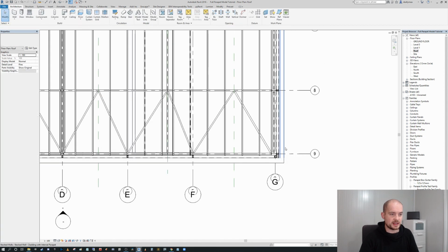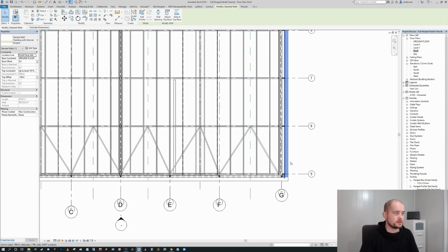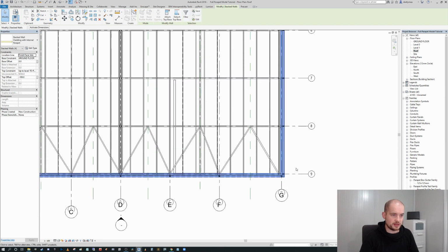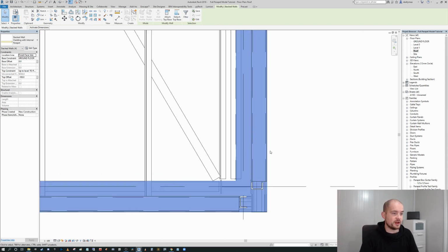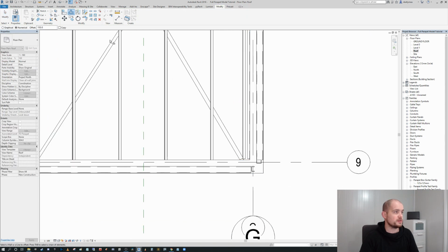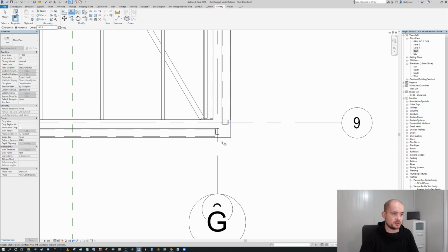And as you can see, that's actually after offsetting out the way rather than in the way, okay? So I'm going to tab select all that, and I'm going to press return or spacebar, sorry, and that's going to flip the orientation. And then finally, I'm just going to give that another offset value. So I'm just going to select numerical, 100 mil, perfect. And I'm just going to offset that value. I'm just going to select one wall, and I'm going to tab. So you can see that the boundary walls are completely highlighted. I'm going to select that.